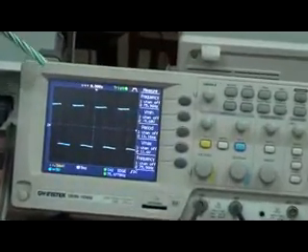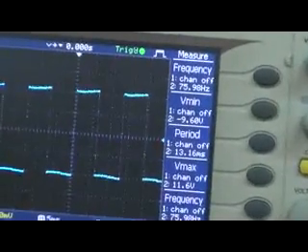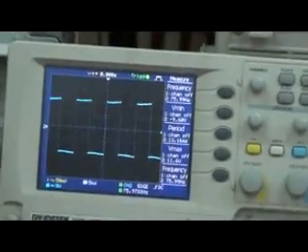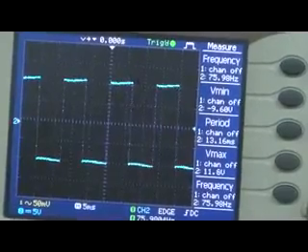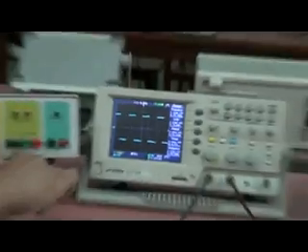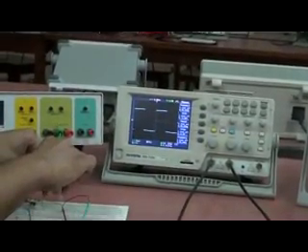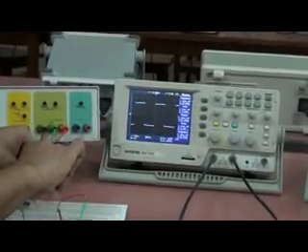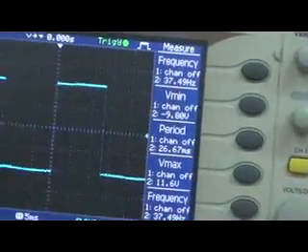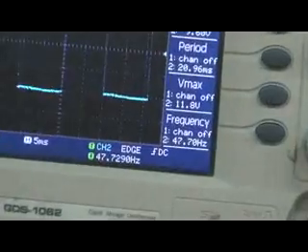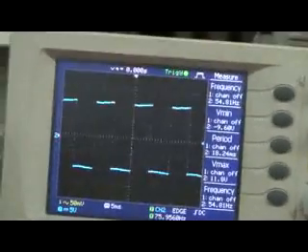The square wave is the output of the Astable circuit that we are using for generating the waveform. We can change the frequency of this waveform using the potentiometer, that is the pot, by rotating its knob clockwise or anti-clockwise. By changing its knob, we can observe on the DSO that the frequency of this output waveform generated can be changed.